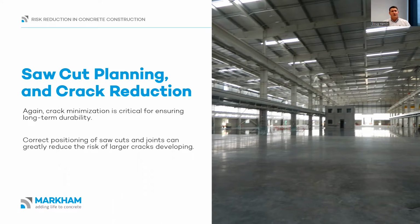So on that, just one more point with the cracking, I mentioned it earlier, I really want to touch on it: if you do leave a concrete slab with cracks in it, that fast tracks the pathways for contamination to get into the concrete and starts that corrosion process of the reinforcing steel off quicker. So, I mean, you see it a lot on construction sites, a rust stain coming out of a construction joint or a crack, something like that. And often it's happening long before the building's actually even finished.